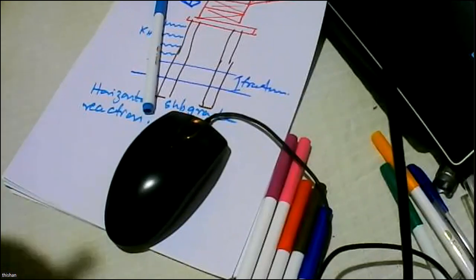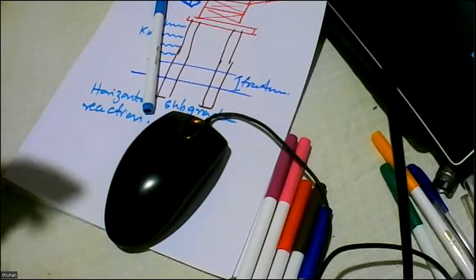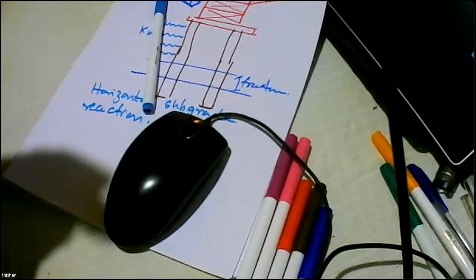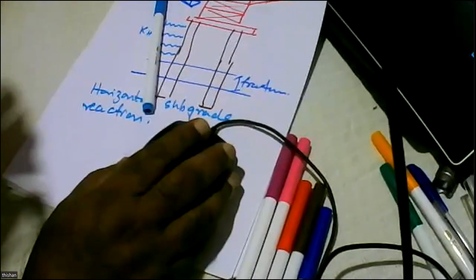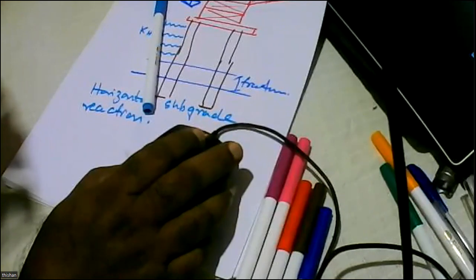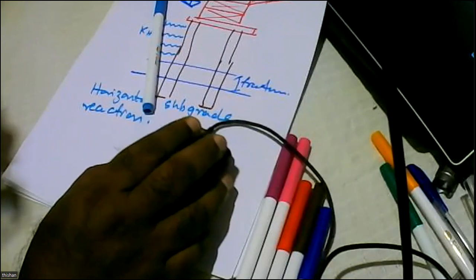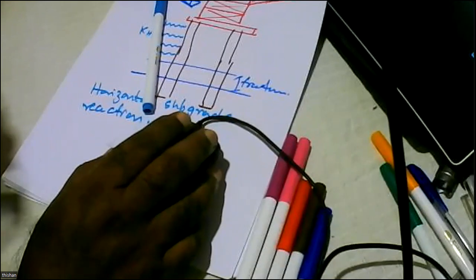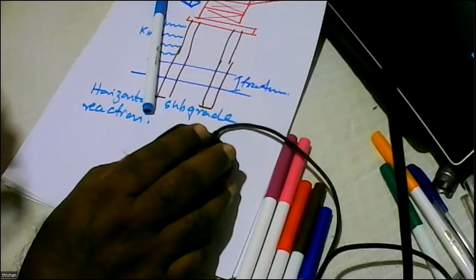When the SPT value is 8 to 15, we call it stiff soils. When it is 15 to 30, we call it very stiff soils. And when it is greater than 30, we call it hard soils. So basically, a lot of testing has been done to determine the cohesion of soil, and when you do a lot of testing, you will find the cohesion of the soil comes pretty close to the 4.5 to 5 range.